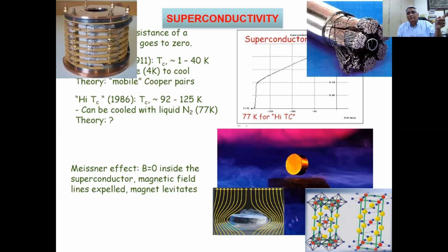So it's not that you can produce infinite magnetic field by increasing the current flowing through these coils. No, there is a heating effect there. So the current flowing through a set of coils is limited by various factors. It's limited by the gauge of the wire used to make that coil. So that's why if you see an electromagnet, even to produce 5,000 oersteds, right? What is the higher value of a magnetic field?